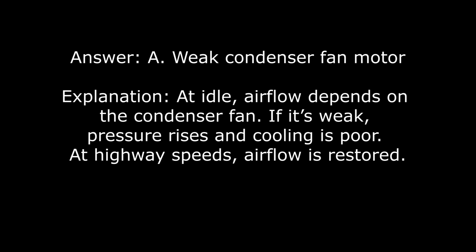Answer: A. Weak condenser fan motor. Explanation: at idle, airflow depends on the condenser fan. If it's weak, pressure rises and cooling is poor. At highway speeds, airflow is restored.